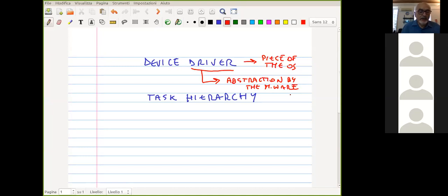So you can, for example, define a driver for the famous laser rangefinder, and you put in your concurrent code of the robot a driver of a virtual machine or virtual sensor that is called rangefinder, so that if you change the robot software, I mean, you may use a SICK, I told you yesterday, the most common industrial laser rangefinder, or a simpler system like Hokuyo.